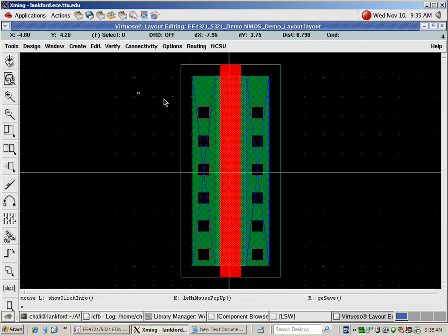So it's really simple for us to do the layout, because this kind of cell is called P cell. P cell means parasitic cell. So the foundry already designed some smart computer software for you. You just need to specify the width and the length, then we get the transistor. However, we have the transistor, we have gate, source, and drain.